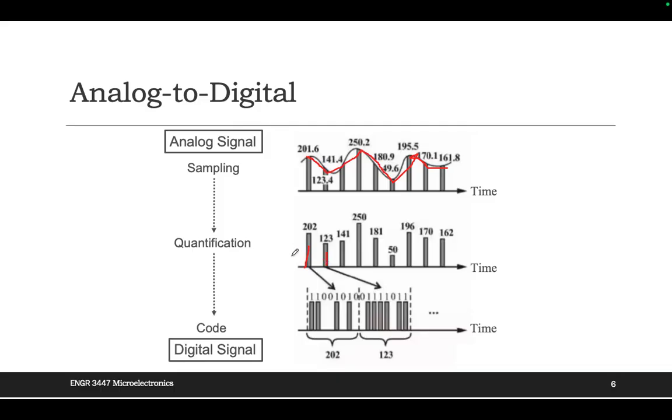After quantification, we have the 8 a.m., 9 a.m., 10 a.m., 11 a.m. values, like 92, about 100, 82, 23. If our microcontroller wants to deal with them, we need to transfer them to digital. Am I right? Because the microcontroller, like I said, just reads 3.3 or 0.